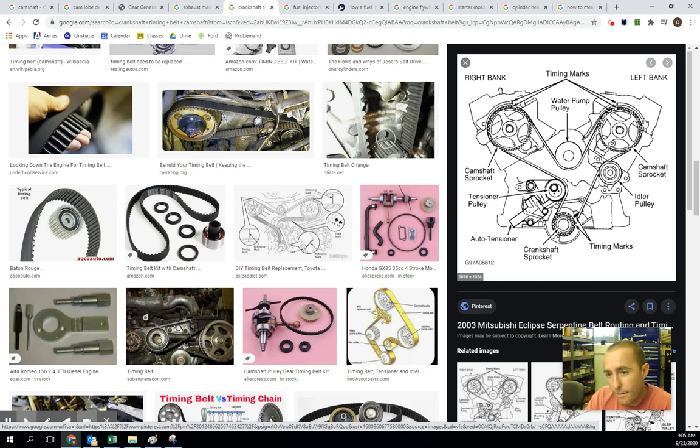So if it's rotating this way and this belt is coming down here, if I just made that run right there, I probably didn't have enough tension on that belt. By moving the belt in here and coming at a more aggressive angle, that allowed it to bite on this sprocket a little better, so I can get good contact with that sprocket. Whereas if I came right through here, I'm not hitting that sprocket till down here. I'm not having good contact there. So idler pulleys help with positioning of the belt and help with tension.